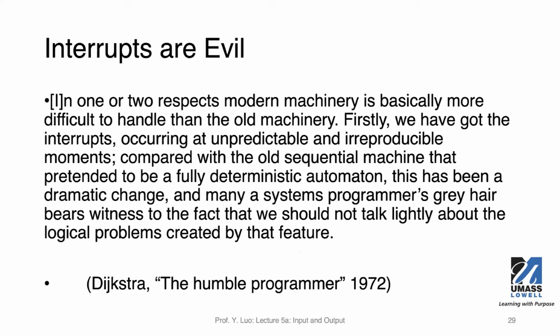Firstly, we have got the interrupts occurring at unpredictable and irreproducible moments. I think those are the two key words you may want to remember if you want to remember something from the slide. This is really saying that the interrupts are asynchronous. You don't know when they're going to happen, and you oftentimes cannot reproduce.